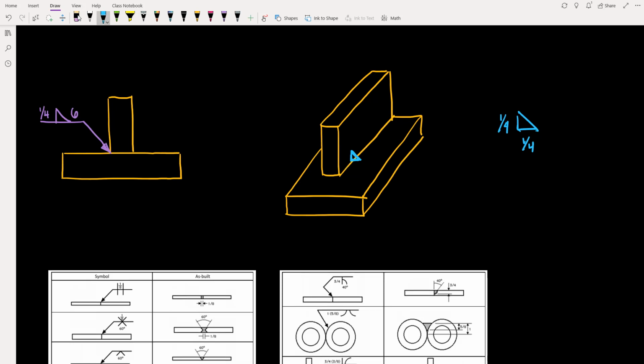Next we have the 6-inch dimension, which refers to the length of the weld. So the length along this member will be 6 inches. So all of this will be weld. It's also important to note with weld symbols that we never place the dashes to indicate inches. It's just understood that these numbers are given in inches. So we can remove those dash marks to simplify our detail.